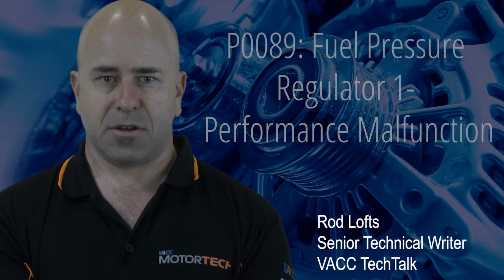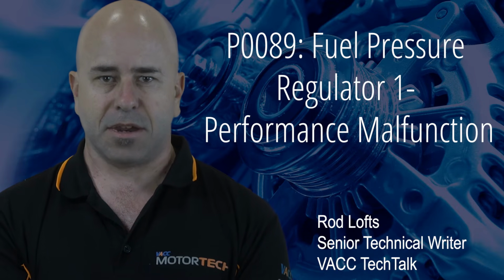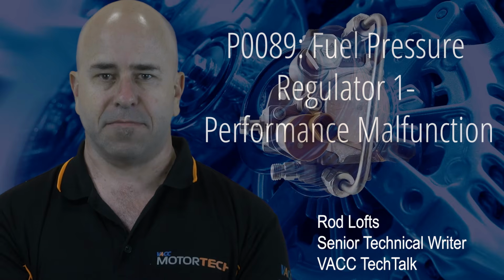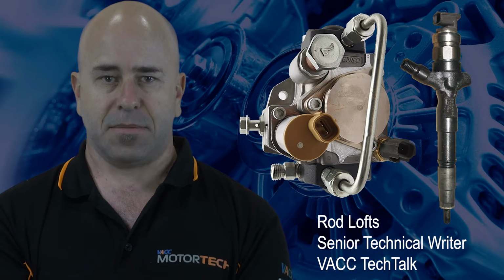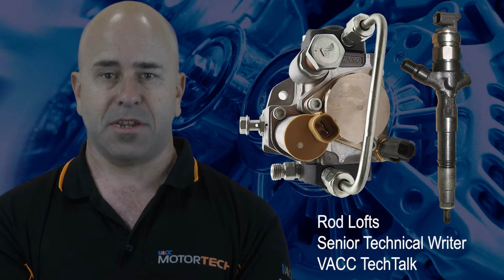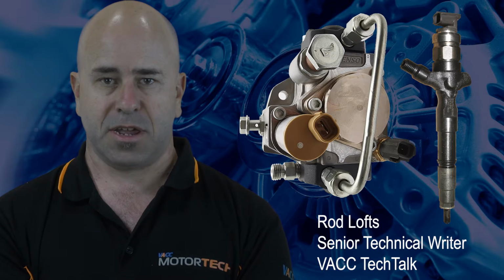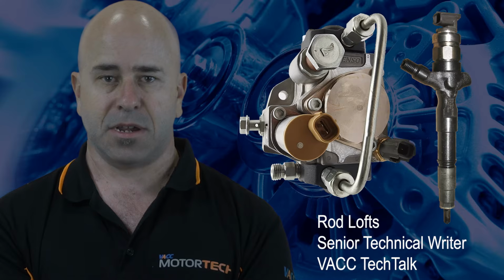P0089 is a generic diagnostic code that can be recorded on many modern diesel engines and is not linked to any one component failure. We have received feedback about thousands of dollars of fuel system components being replaced, only to have this same fault code return. However, a thorough diagnostic procedure and checking some easily overlooked areas might help you find the cause of this code.